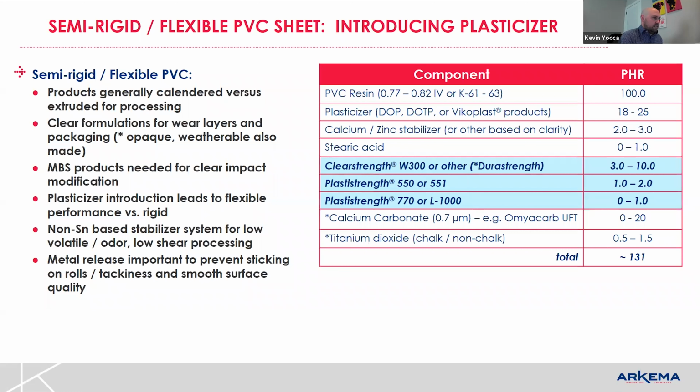I'd really like this to have more melt strength or fuse faster for me. In the flexible world, I think you're right. A 1-pack of stabilizer and then lubricant, or sometimes those things are combined, are pretty typical. And then the plasticizer, obviously, in PVC.